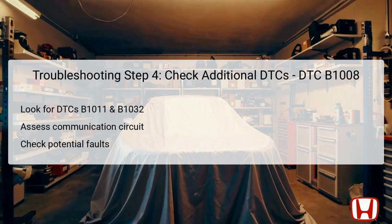An open circuit could be due to damaged wiring or faulty components, which would need immediate rectification. If the circuit is indeed compromised, appropriate repairs or replacements must be made. On the other hand, if the circuit appears intact, it may point towards a faulty MICU, necessitating its replacement to restore proper functionality.